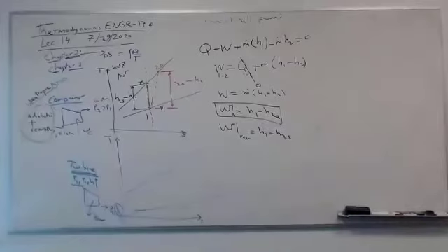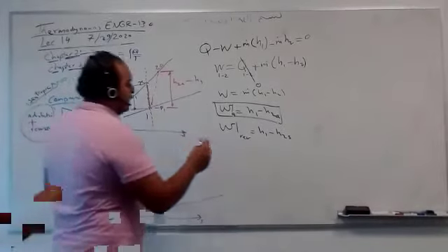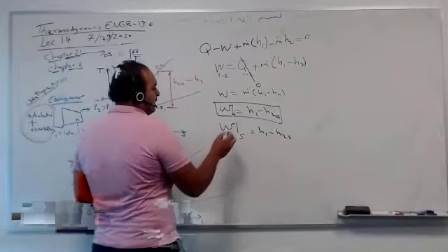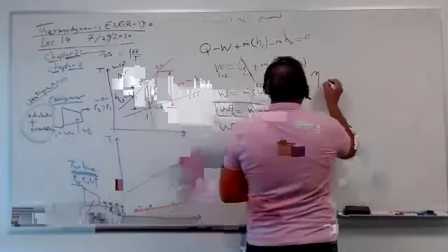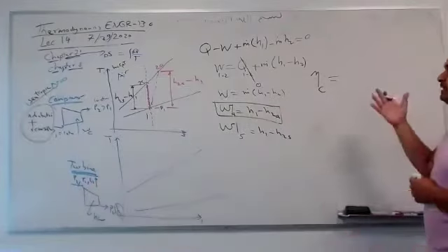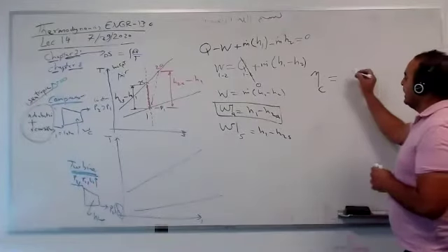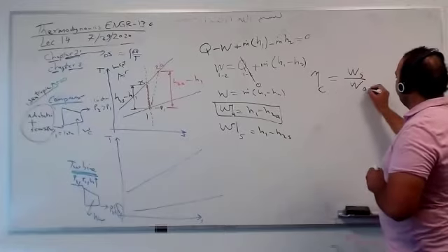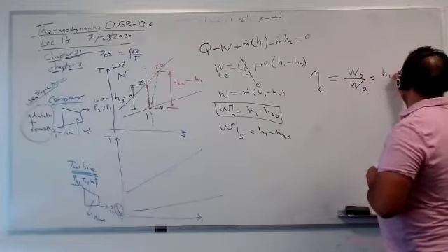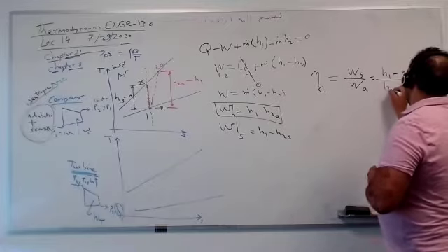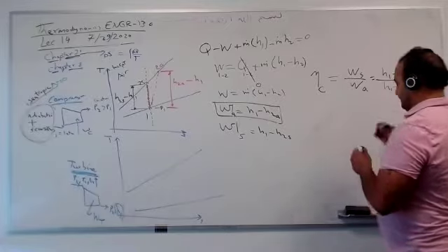So we're going to define the efficiency now. Efficiency, for example, we call it isentropic or actual. The efficiency of a compressor is 80%, 90%, and we wish it to be 100%. It's W_S over W_A, which is H1 minus H2S over H1 minus H2A; the sign doesn't matter.